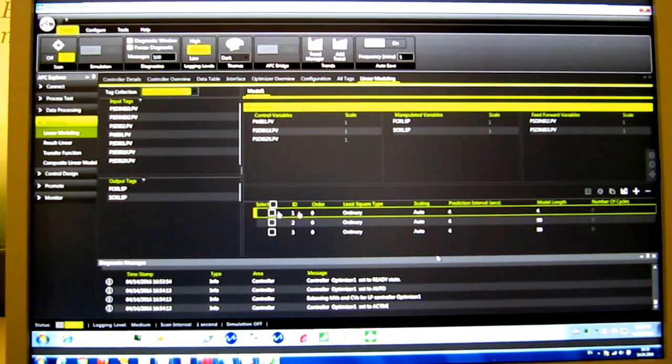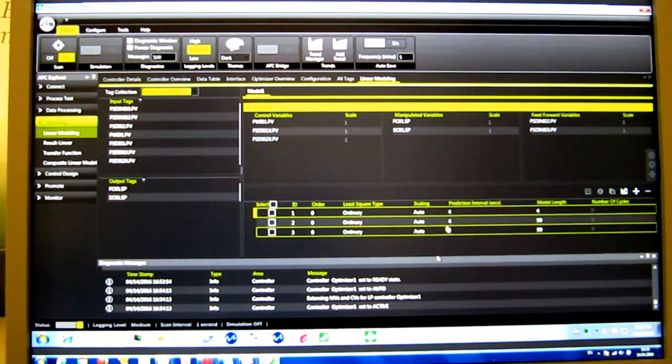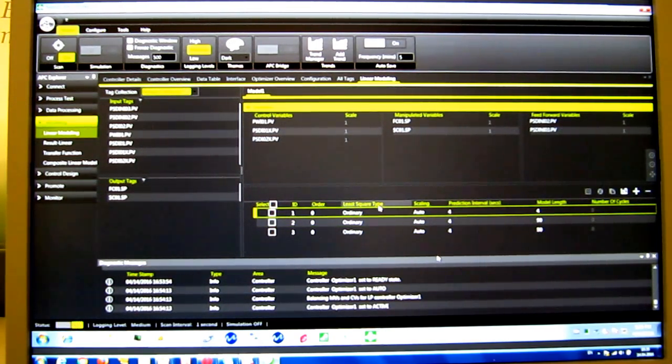And then what I do is I run through here a sequence of identification processes. So normally this is sort of the default prediction. It has a recursive, partial. I won't get into any of these details, but basically what this process here is doing is using the data that you've generated, it identifies models. There are 2 main types of identification techniques. One is the finite impulse response, FIR, and the other one is ARX.